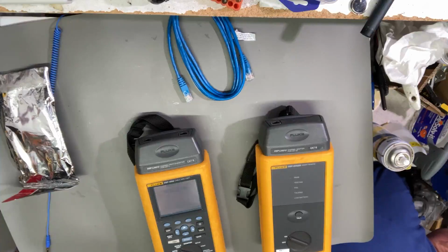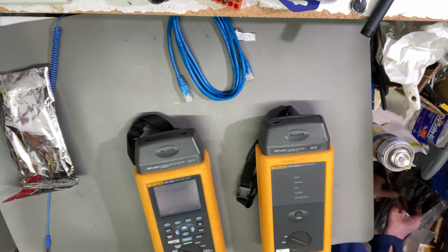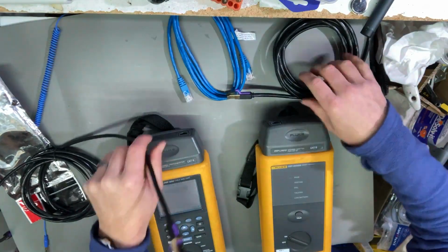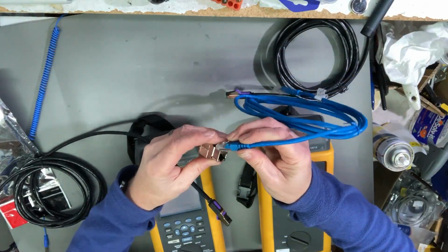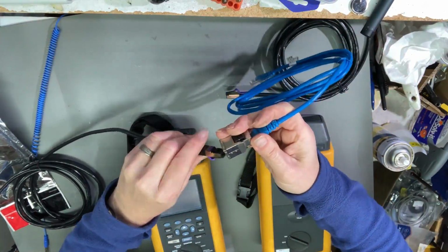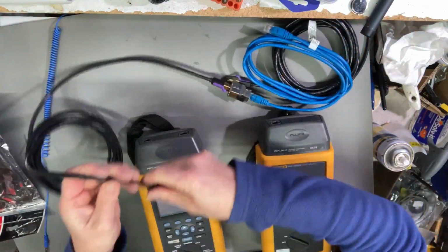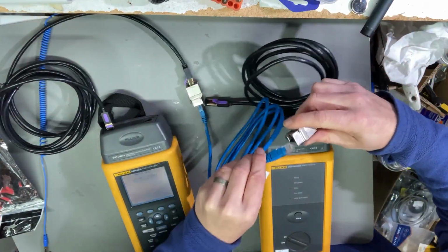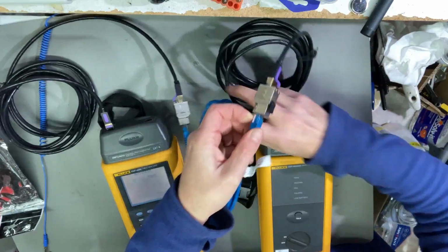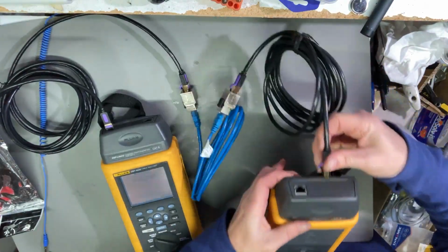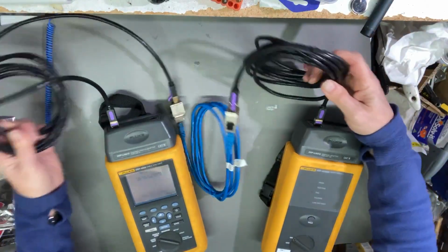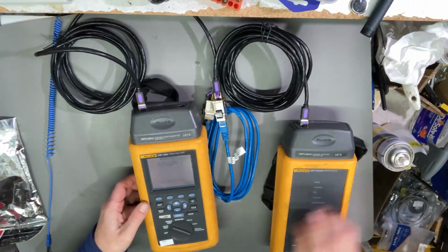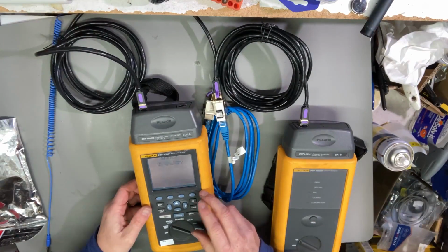So if that's the cable under test, I'm actually going to add a couple of cables at each end. This cable analyzer needs a couple of meters of cable to do its analysis properly. The cable under test is this blue one, and I've got some Cat7 cable here which I'm going to plug in there. These cables at each end are 3 meters long, Cat7 cables. They've previously tested okay.